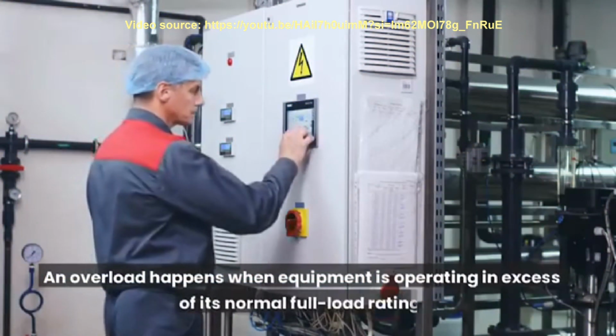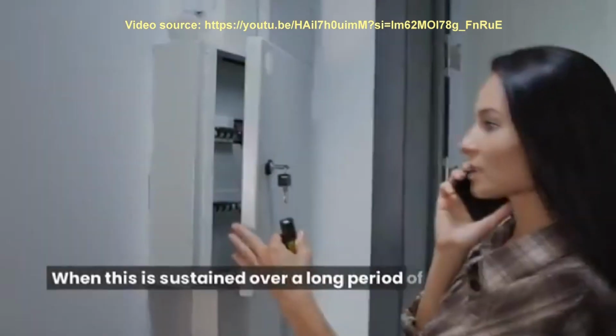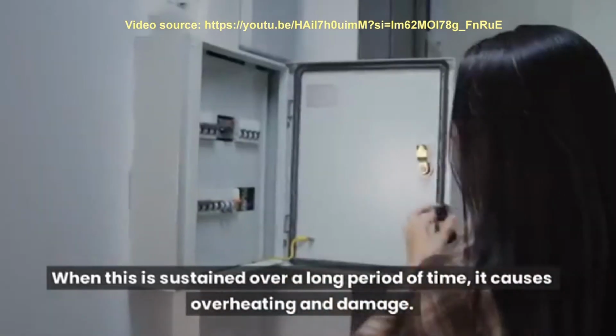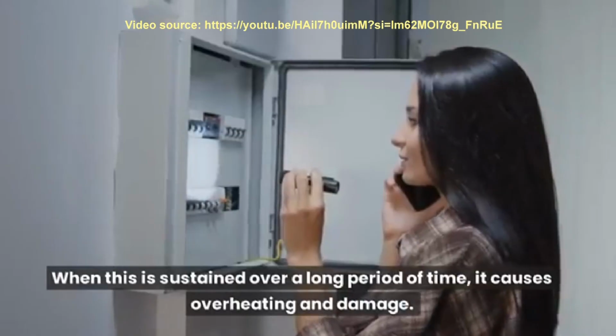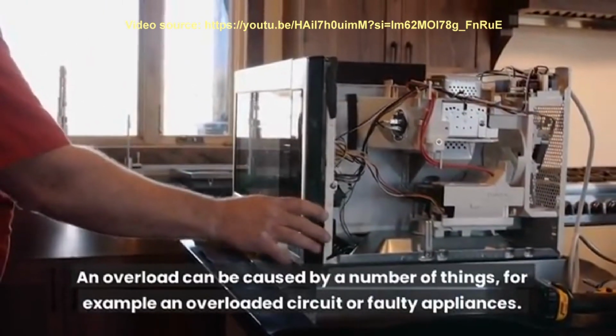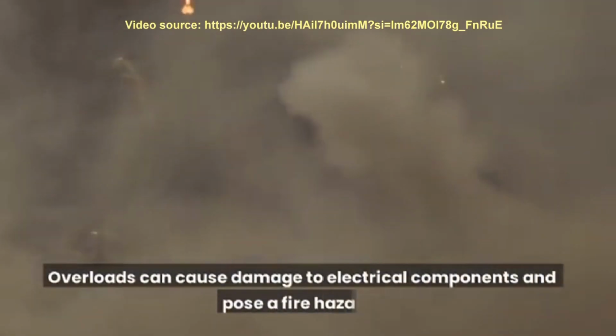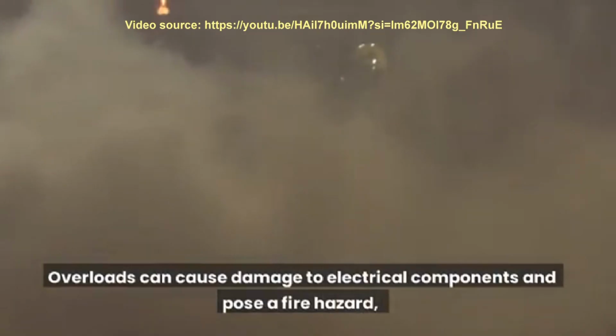Overload. An overload happens when equipment is operating in excess of its normal full load rating. When this is sustained over a long period of time, it causes overheating and damage. An overload can be caused by a number of things, for example an overloaded circuit, or faulty appliances. Overloads can cause damage to electrical components and pose a fire hazard, so it's important to shut off the power to the affected circuit as soon as possible.